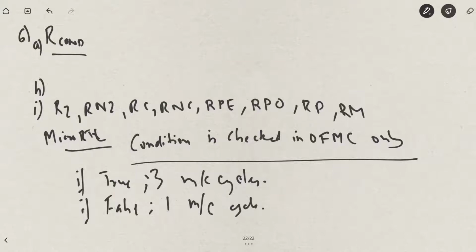So this is how the return conditional instruction is different from the jump conditional and the call conditional. Also know that in this case the opcode fetch machine cycle has 6 T states. Fine. You'll see actually the complete micro RTL in the PDF that will be loaded in the classroom as well. So far we have studied 6.